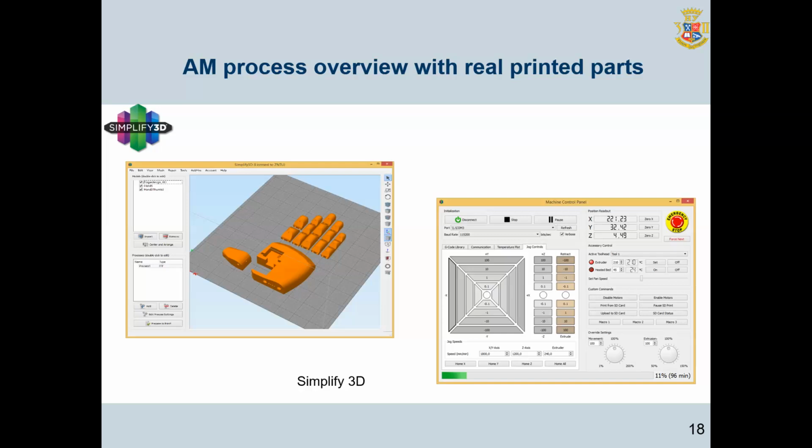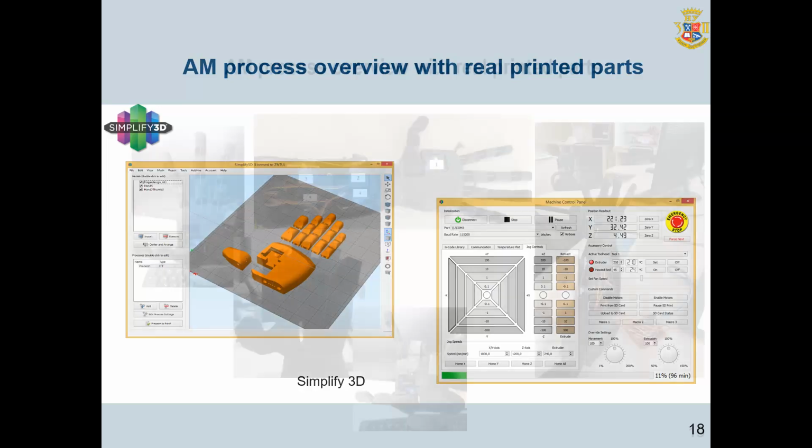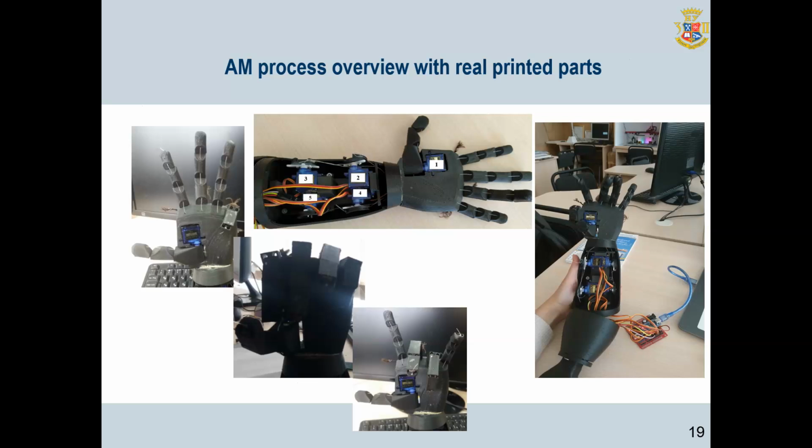The mechanical parts of the designed physical prototype, fingers, palm, base, or the thumb, can be made using fused deposition modeling additive technology. The Leapfrog Creator printer uses non-toxic ABS plastic, which is resistant to adverse operation conditions and has a low cost. A general view of the developed, printed, and assembled prototype of the robotic arm is presented on the slide.